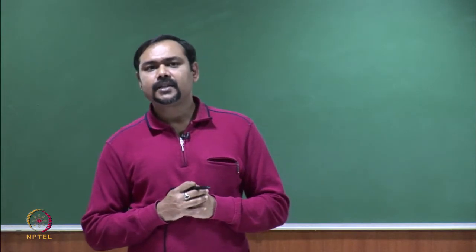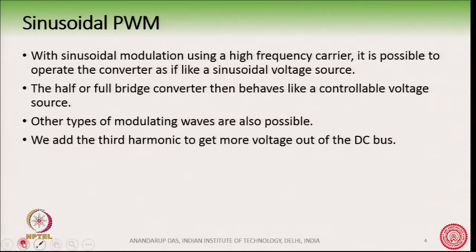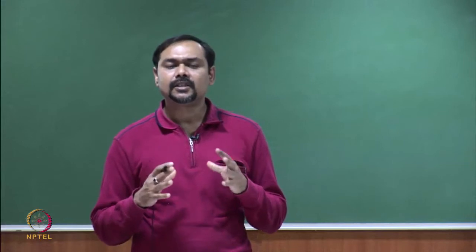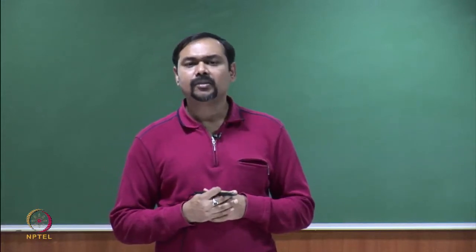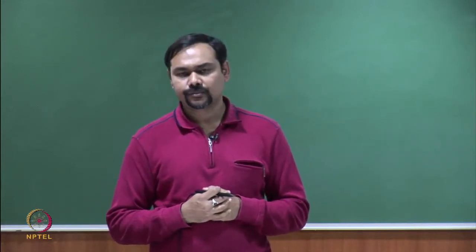After this, we studied sinusoidal PWM. In sinusoidal PWM we compared a sine wave with a high frequency carrier. And with that what did we achieve? We operated the converter as if it is now working as a controllable sinusoidal voltage source.